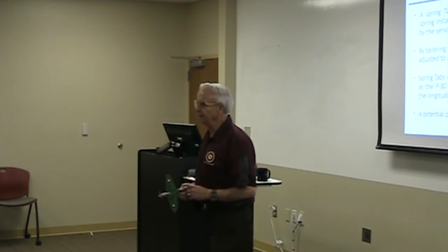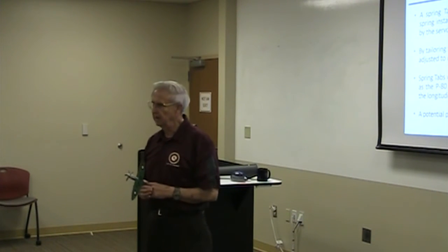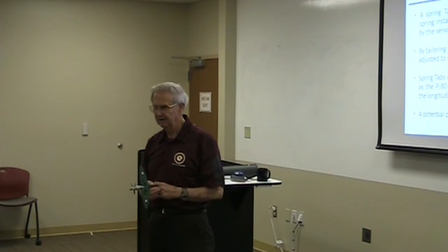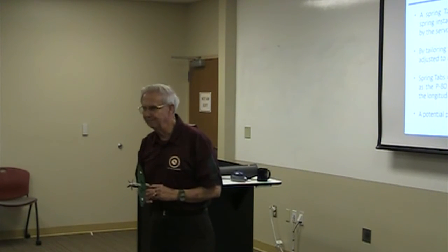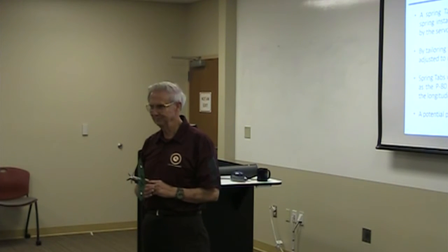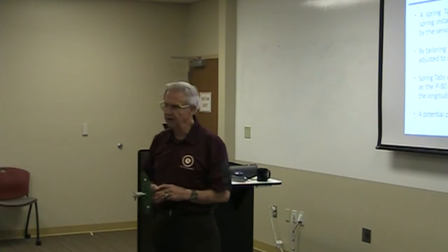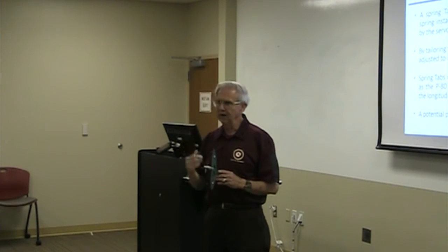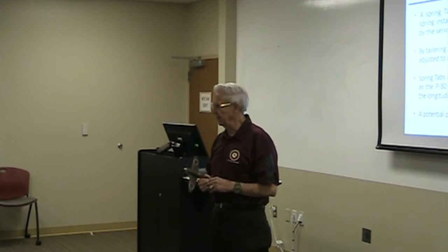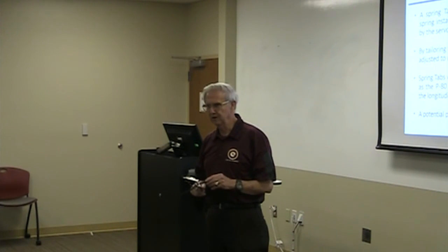We went down the tunnel, in the tunnel we had a high-speed movie camera. And by high speed, I mean 2,000 frames per second. That camera captured 120 frames of film. Knowing the startup time on the camera and those kinds of things, they were able to determine that this flutter started and went away in 0.3 of 1 second. So you don't want to have a flutter experience if you can avoid it.